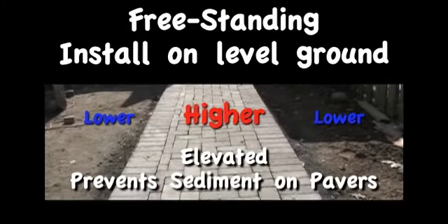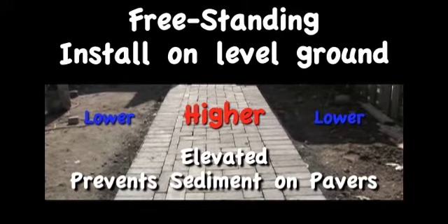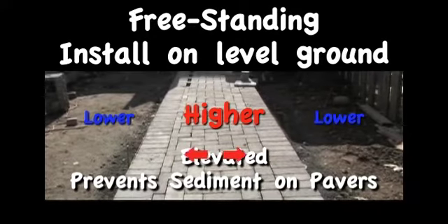load-bearing areas. A freestanding paver structure should be designed so that the pavers are elevated relative to the surrounding landscape. Elevating the pavers prevents soil and sediment runoff from collecting on the pavers, which may cause clogging.